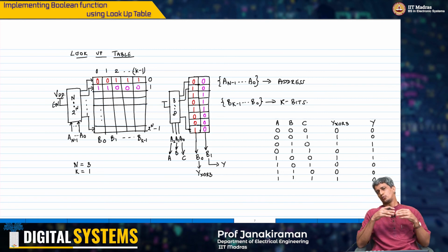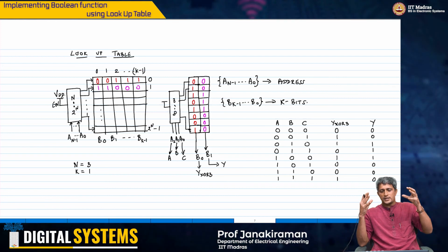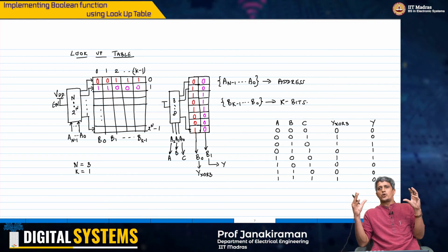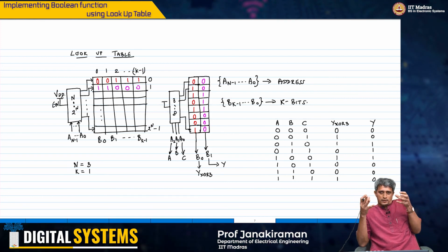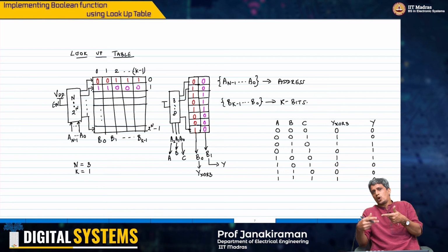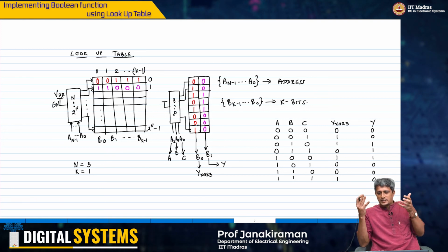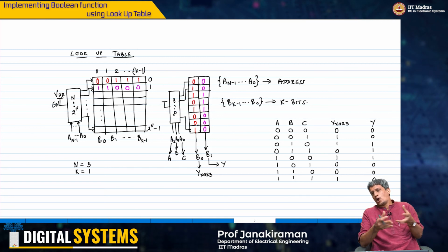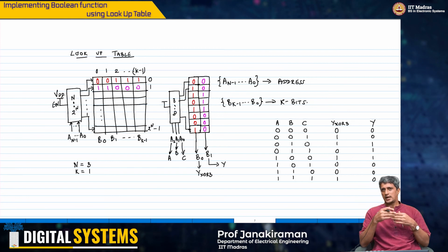The idea is that given a logic, you can program the functionality on a hardware. Each time you want a new logic, you can program it differently. So this kind of logic is not implemented using elementary logic gates. They are implemented using these lookup tables and other such techniques.